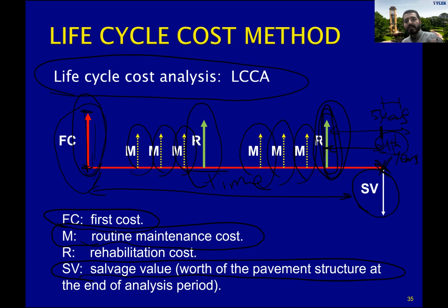I can crush that aggregate or that hot mix asphalt surface and mix it with a new hot mix asphalt mixture at somewhere between 10 and 15% by weight, and reuse it again. If that pavement was fully exhausted at the fifth year, then maybe it is very oxidized. There is no need to use it, otherwise it might actually reduce the performance of the new structure if I incorporate such material.